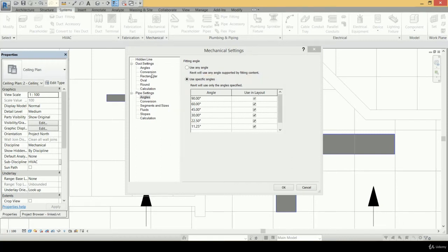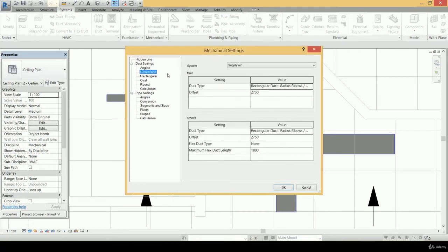And after that, for the ducts, we have the conversion branch here. And at that conversion module, we need to specify the initial duct type. So if we draw a duct, you see it's drawn automatically with the rectangular shape, but we can change this initial type to, the oval, for example. So if I select that one, I can change it to the round type, or I can select it again for the oval type, for example, and so on.